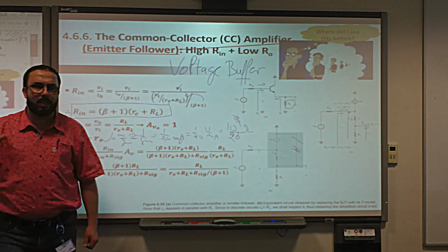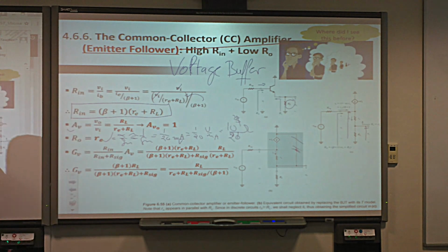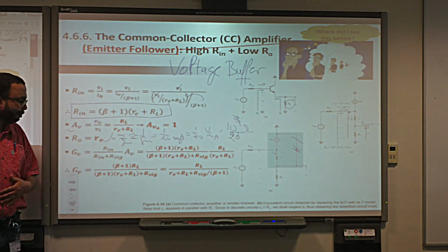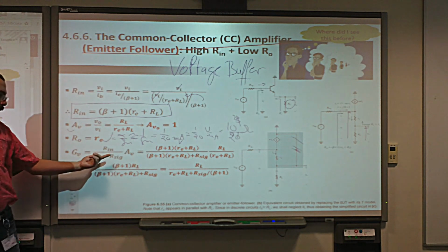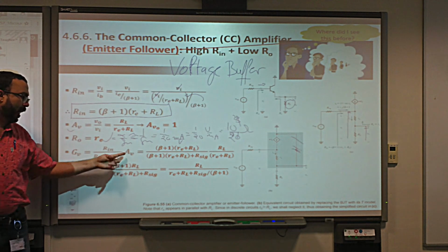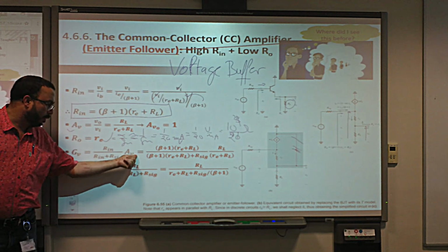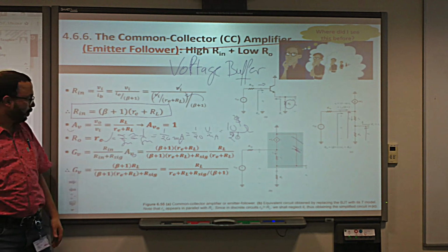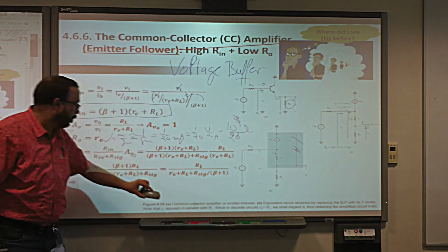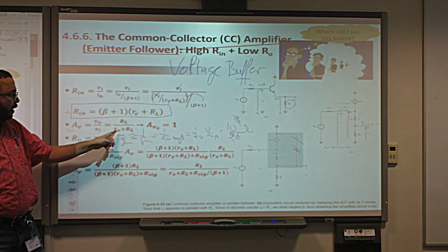Bingo, we have the 3 conditions verified. Excellent. Now the only thing remaining would be the overall voltage gain. Again, we apply the formula here: the voltage divider at the input times the voltage gain, or this times the open circuit voltage gain times the voltage divider at the output. Both formulas we can apply. We can apply this one. We have this already, we calculated it just now.